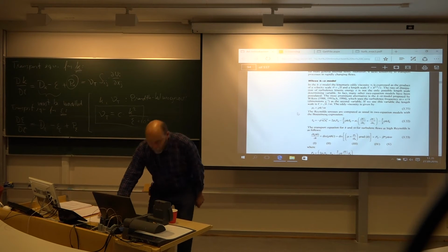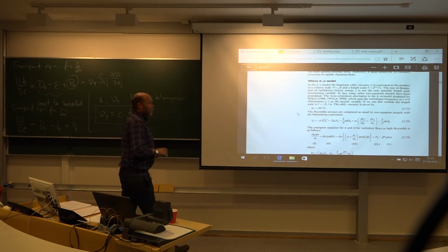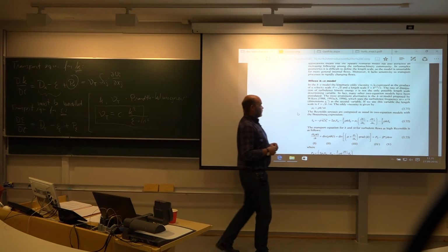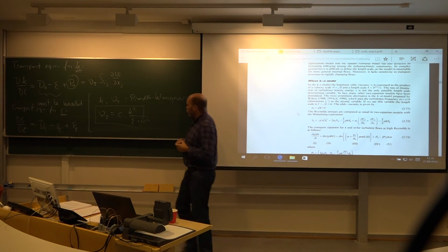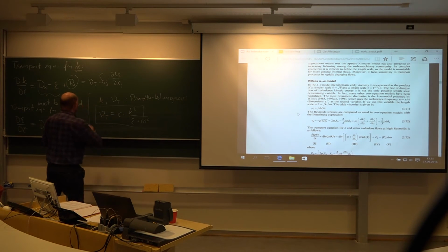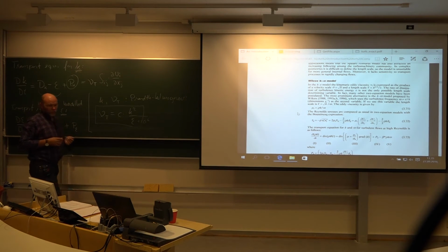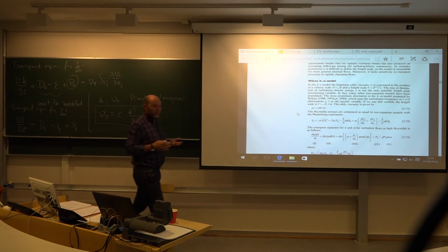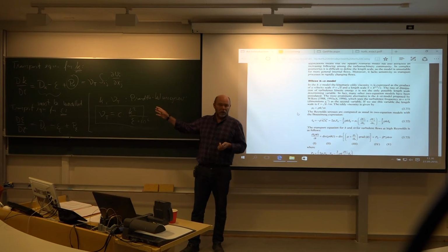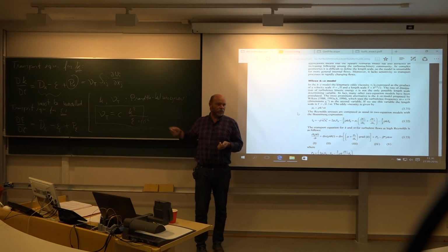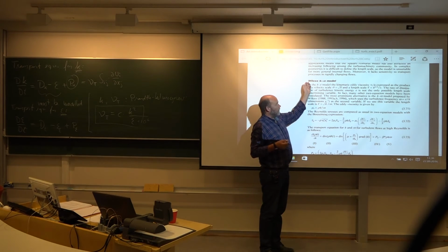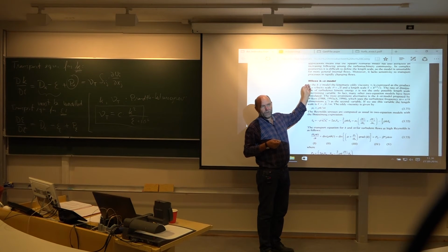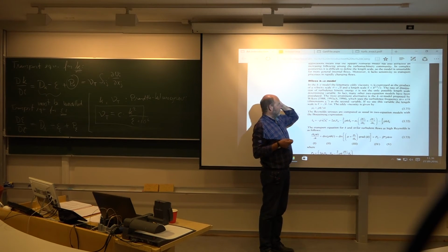The K omega model, very popular, just as good as the K epsilon, and in many instances actually a lot better. So the sad thing was that the K epsilon was sort of the first 2 equation model, quite advanced model, that actually succeeded. So a lot of people used that one from then on, and we have a lot of reference material with K epsilon. K omega came later, so it's not that well investigated, but in many cases it's a much better model.